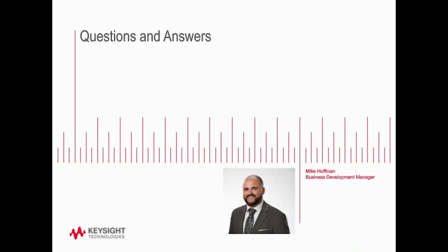So if you're just doing something on the side, maybe on a signal that isn't on screen or isn't scaled properly or stable in reference to what you're triggering on, that's where the counter would be more useful. They're very complementary: the measurements are for what's on screen right in front of you, while the counter can be used for a much wider variety of options. The counter can also measure up to 3.1 gigahertz, where the measurement function is limited to the bandwidth of the scope that you have.